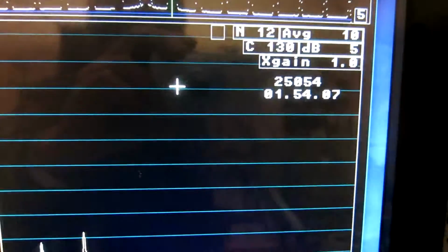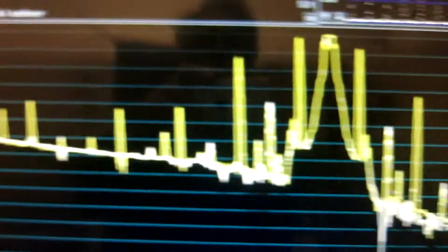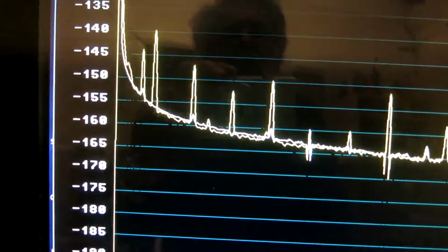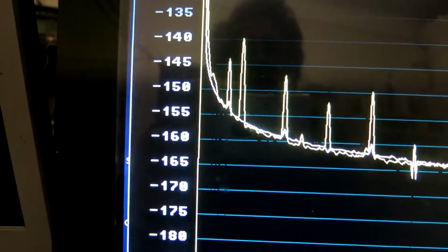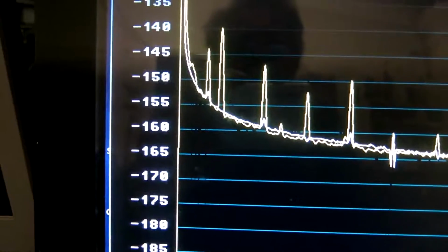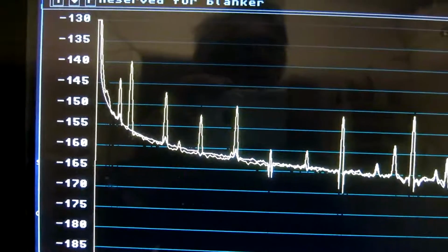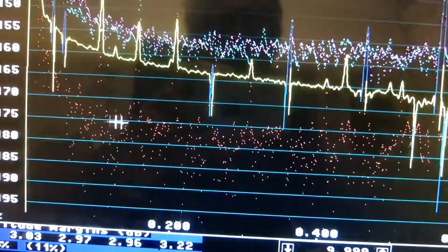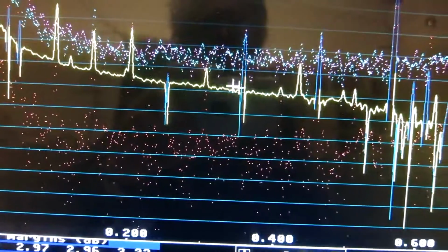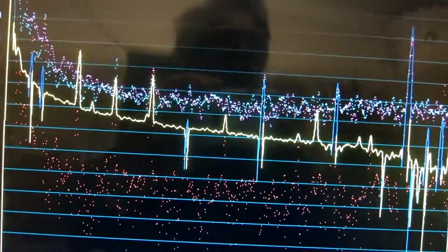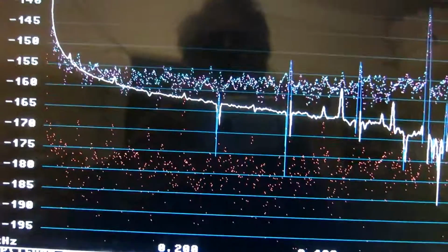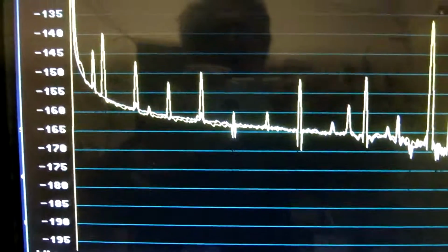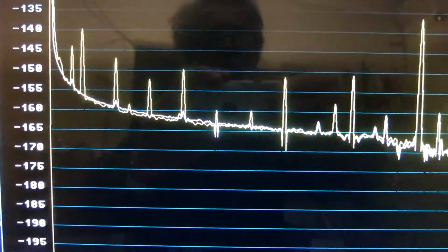Here is the result for the power amplifier after nearly 2 hours. It is quite unexpected. There are no narrowband noise bursts, and the phase noise and the AM noise are fairly low. I will read these values, but first demonstrate what the full information is. Here you can see for phase noise the imaginary part is far below the real part, so the yellow curve here is accurate. For AM noise also. So I can read the data from these curves and compare with the result of the Wenzel oscillator without any amplifier.